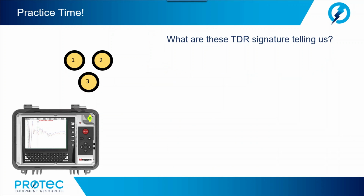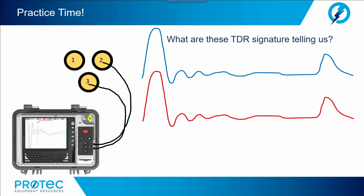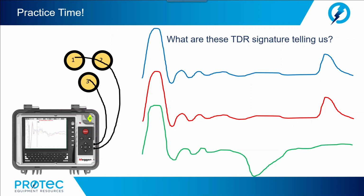All right, let's do another one. So, 3 conductors, what are these TDR signatures telling us? We connect between conductor 1 and conductor 2, and we see all the way to the end of the cable. We connect between conductor 2 and conductor 3, and finally, we connect between conductor 3 and conductor 1. So, observing these 3 captured waveforms for comparison, type into the question function, what is the nature of the fault that we see here?